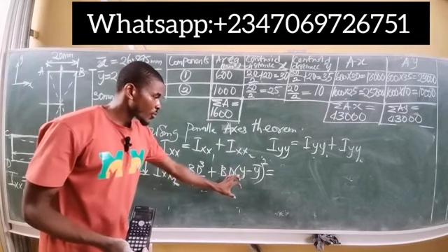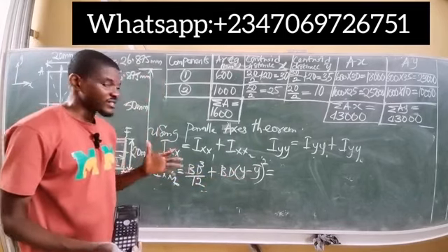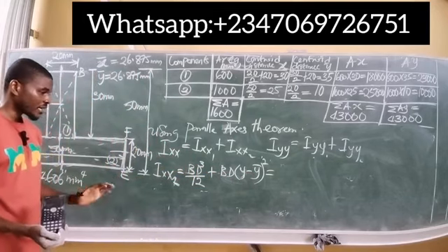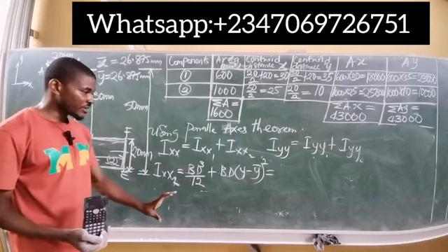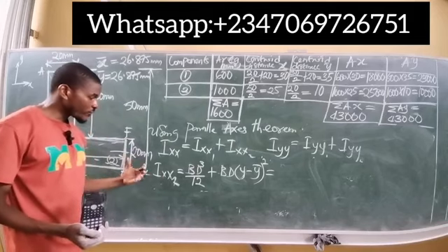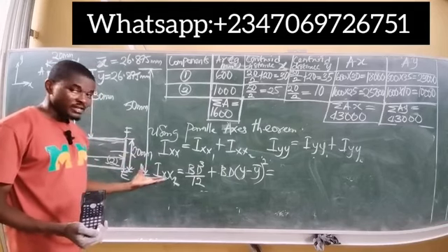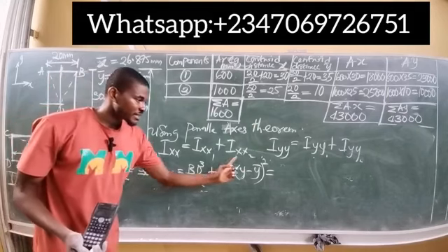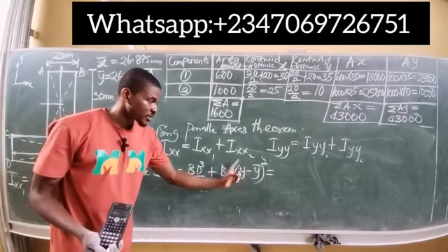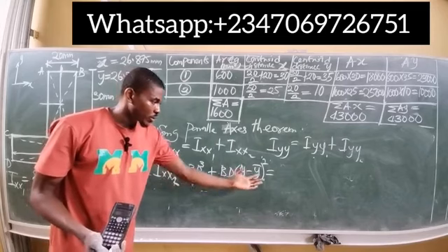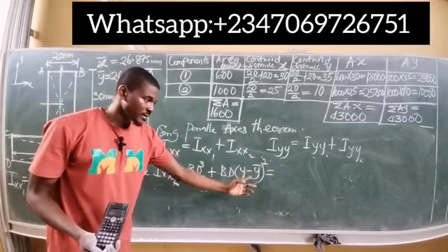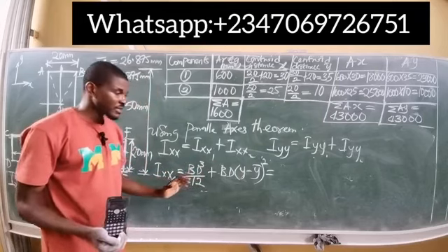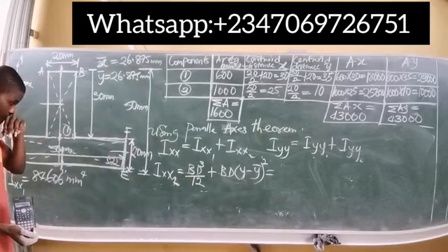Now it's going to be y minus y bar for the second segment. That's the only difference. And of course, bd cube here has to be for the second segment as well. Everything still remains the same. But notice that if you're looking for the moment of inertia for the second x segment, you have to subtract in this bracket the central distance y and the centroid in y. So it has to be y minus y bar. If you're doing it for y, then here it has to be x minus x bar, or the same order, everything remains the same. Let's try it now and see.